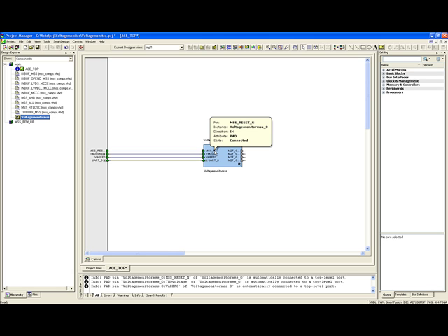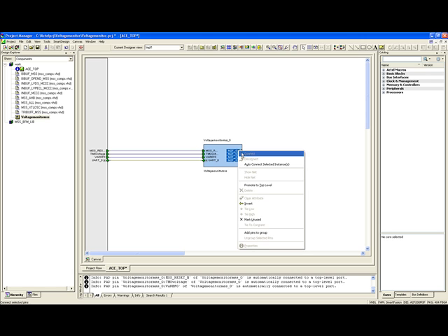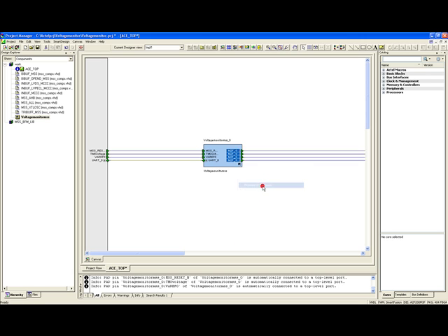Now highlight the GPIO ports 24, 25, 26, and 27 by dragging the cursor over them and then right-click and select Promote to Top Level. It is at this level that you will assign these top-level ports to package pins by going to the toolbar, selecting SmartDesign, and then Show I/O Attribute Editor View.